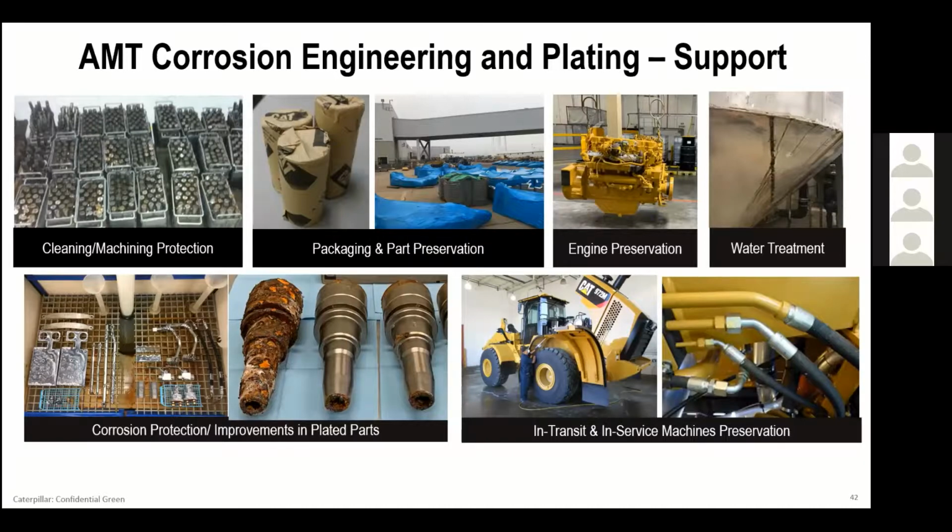We can also take those volatile corrosion inhibitors and fog them in. As long as you're containing the fog and making sure that it's not going to escape, it'll go through the system, depending on if it's an easy pathway, and microscopically protect those surfaces.